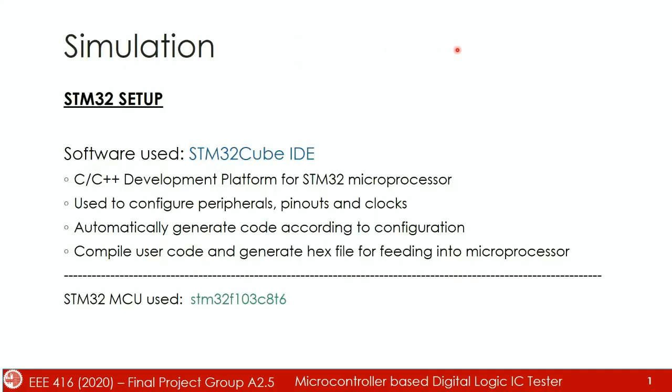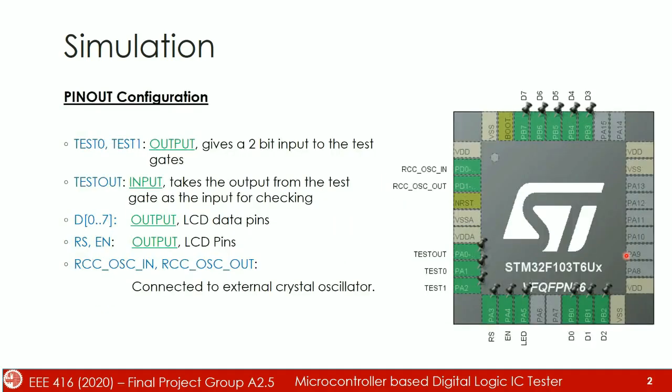I am Fahim Mashur and now I am going to talk about the simulation part of our project. For our project we have used an STM32 microcontroller, STM32F103C8, and for configuring the microcontroller we have used the software STM32 Cube IDE. We configured the pinout and clocks, and finally generated code and compiled it to generate a hex file which will be fed into our microprocessor for execution.